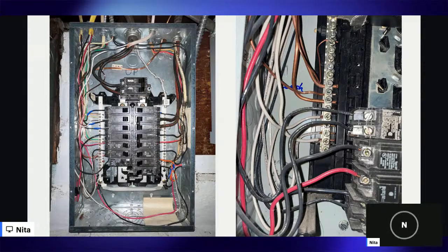Bus bar. It's connected on the bus bar. Where's the other end connected? Is it the ground? The grounding electrode. Yes, the grounding electrode. So in the case that I was using, when we were talking about a ground rod, the GEC. So it is on this right here.